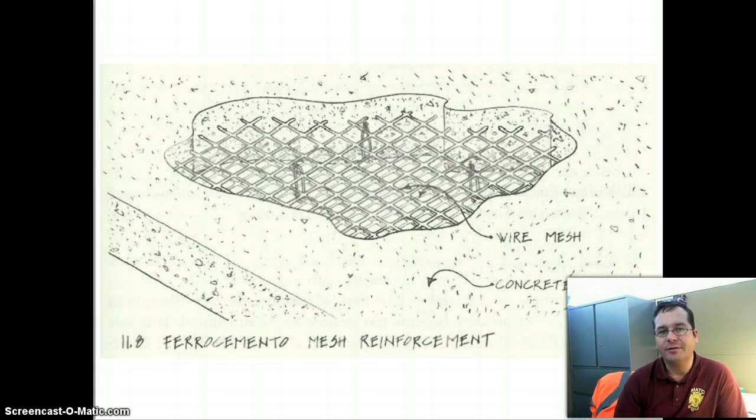This is a composite that was developed by Luigi Nervi, and he called it ferro cement. But by modern standards, it's nothing exceptional. It's just simply a high compression strength concrete with a wire mesh incorporated. He used this in the development of some of his thin domes, which were quite impressive. They could span distances much greater than the equivalent beam of an equal thickness.